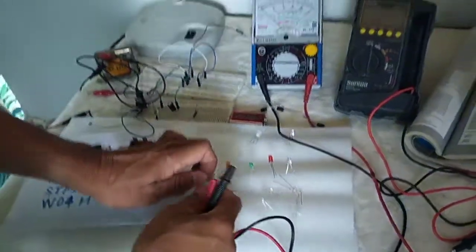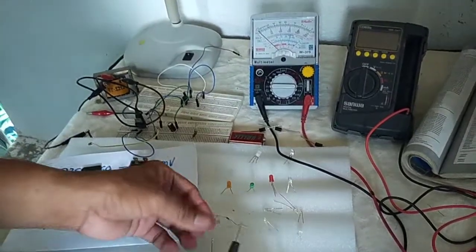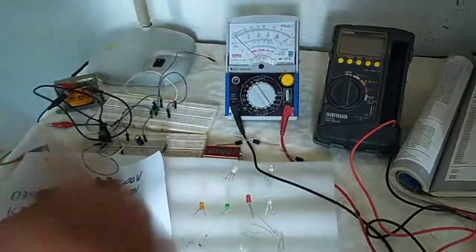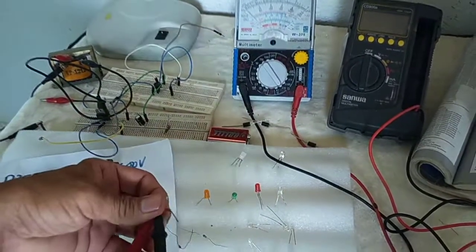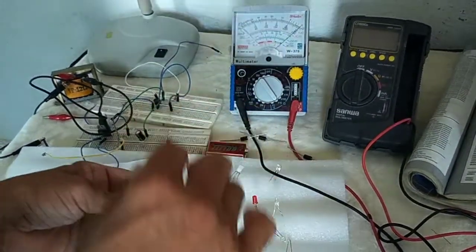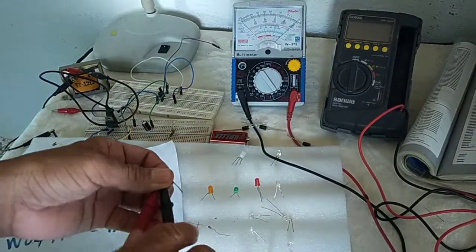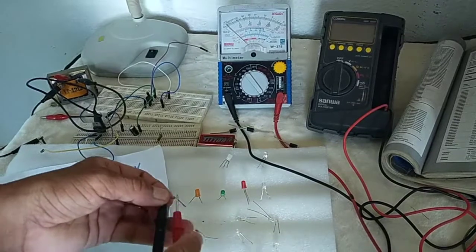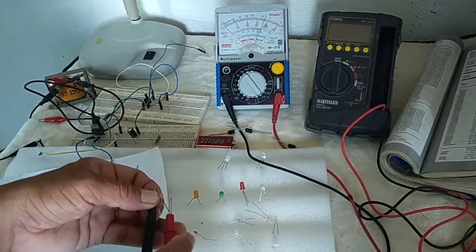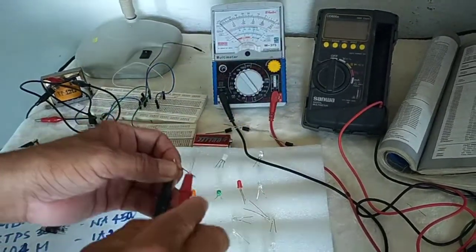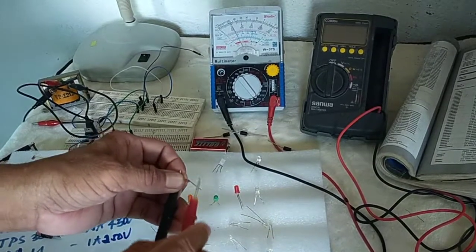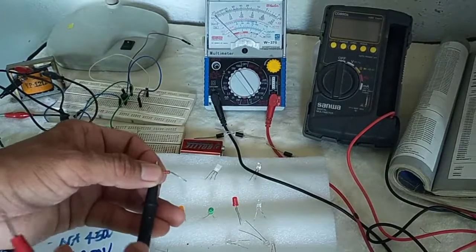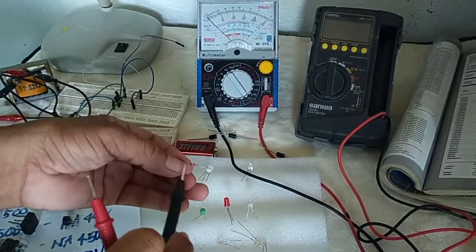Again, before we left, let us review. We have to use times 10 ohms. That is the recommended ohmmeter range when you are looking for the electrodes. Reverse bias, there is no deflection. Forward bias. Focus on the forward bias. So this is the cathode because this is negative for the ohmmeter. And this is positive for the ohmmeter and this is the anode. Anode, cathode.